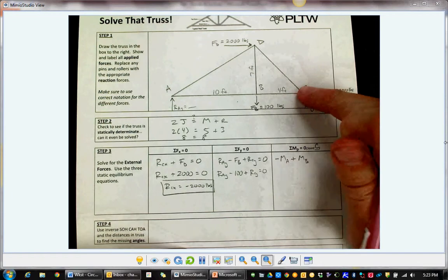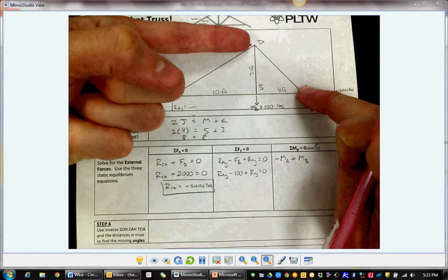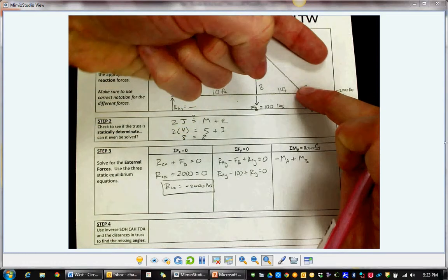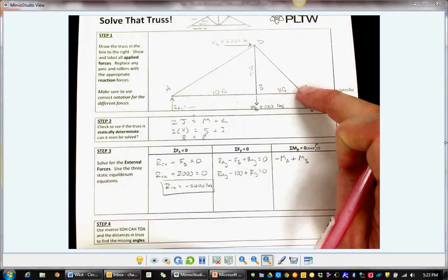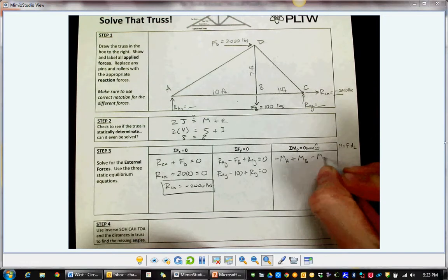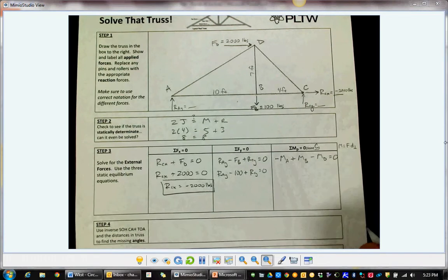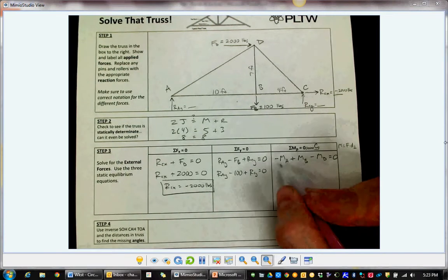So the positive moment from whatever is occurring at B. And the other force that's causing rotation is force D. That's going to cause this to rotate clockwise. That's the negative moment direction as well. So negative moment from what's occurring at D. Those are the three terms. Those have to add up to 0. Now I'm going to take each of these moments and expand them out using this equation, force times distance perpendicular.